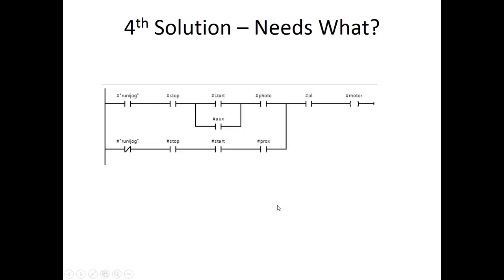The auxiliary contacts probably take care of that problem, but it could be a problem. And then here was a fourth solution. If you just threw this ladder logic into a network, it'd be nice if it was scheduled. And so that's how I showed you that you schedule it twice, or you schedule it once into a function block. But rather than just throwing this ladder logic into just the main, I was looking for a little bit of scheduling on that.